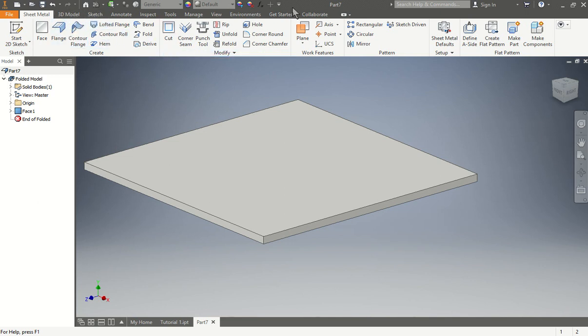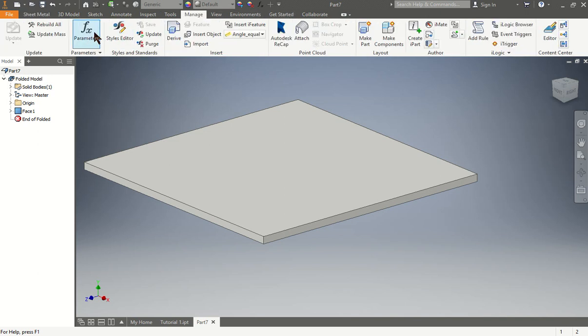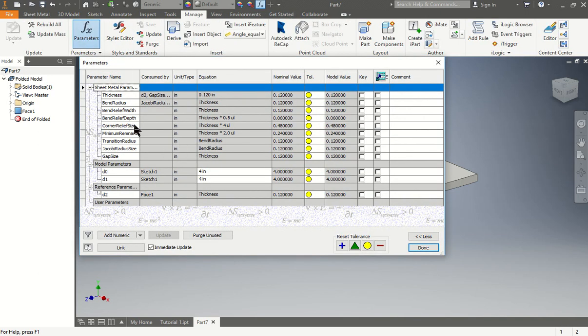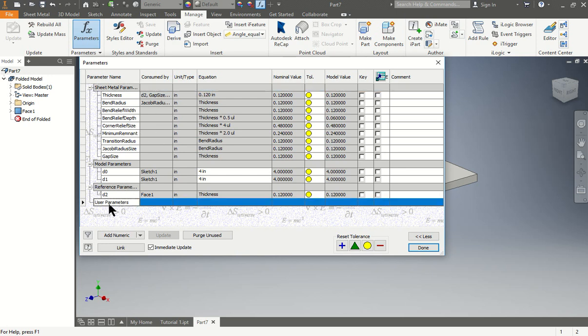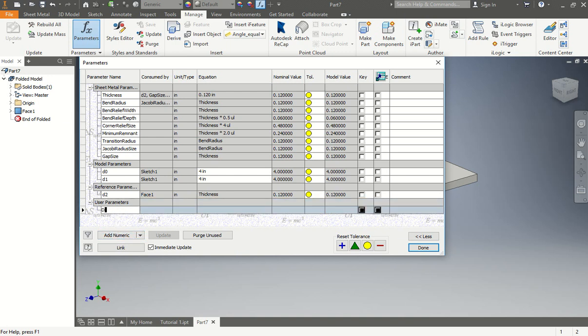Now that that's done, the next step I did is I went to click on, where is it? It was under Manage, under here, right? So now these are the settings that I worked on before. See, before when I did right click, this is what I did. If I go down to user and I do add, I typed in diameter. I'll do it like this so you know it's me, dia, and I'll leave this one at 0.04. Okay, add again, and this one here I'll call it LEN, so you know that's me who just put it. And this one here should be set to 0.12. All right. Once that is done, I can press done.